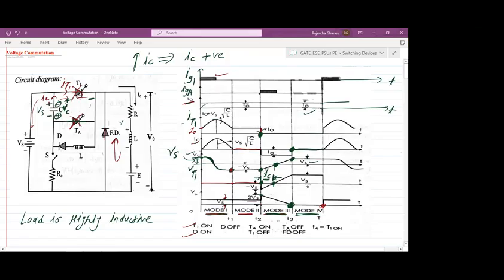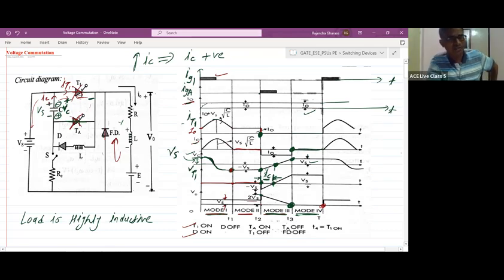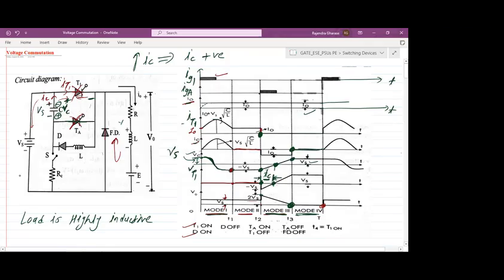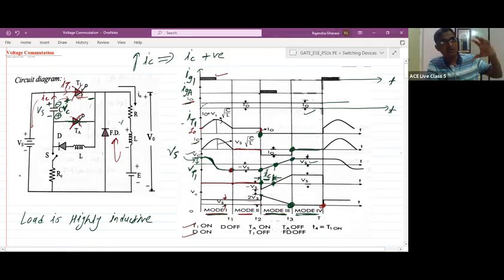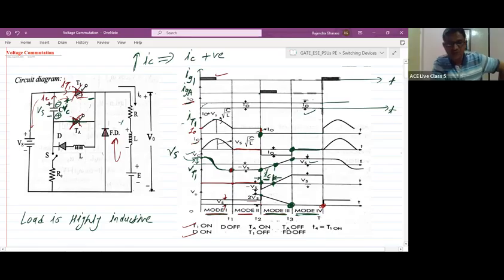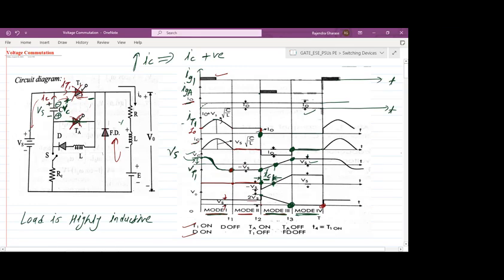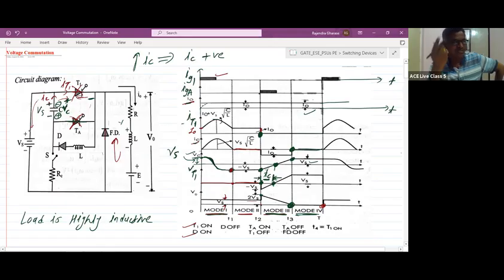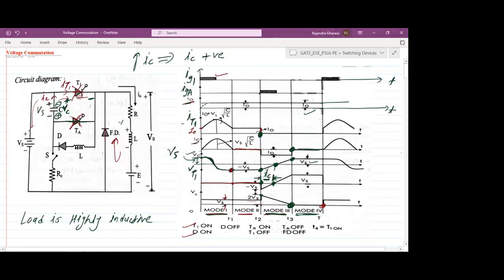Actually, here we have the capacitor and at this side the supply voltage is also there. If we had a circuit with only a capacitor charged to some voltage, and the supply voltage was not in the picture, then whatever you are saying would be true. But here we have the supply voltage also. Due to the higher polarity, our capacitor will again charge. Oh, okay, I understand, sir.